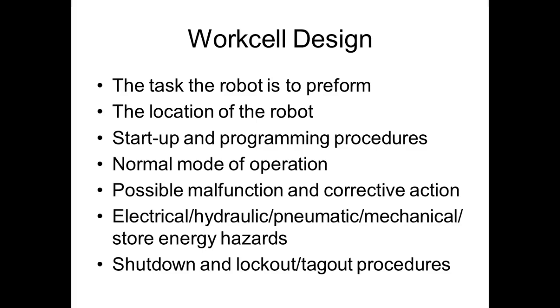Pneumatics hold pressure. How long does it take to bleed that pressure off? Well, it depends on how sealed up your pneumatic system is. So what you need to do is make sure that not only do you disable the power sources, you also bleed off the power sources that maintain their pressure even when their pumps or their compressor motors are not running.